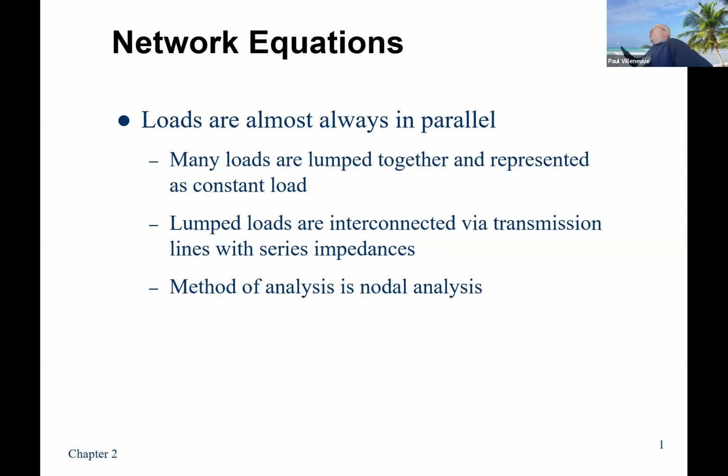And so one of the very first things when you do a systems analysis is you start off with what's called a one-line diagram, which has some basic connection and rating information. You'll take that system, because it's lines, generators, and transformers, and you're going to convert those all to impedances and then start analyzing the system. Well, the fastest way to analyze a system is to convert that to Y-bus. So then once you have it as a number, you can pull out whatever calculations you need.